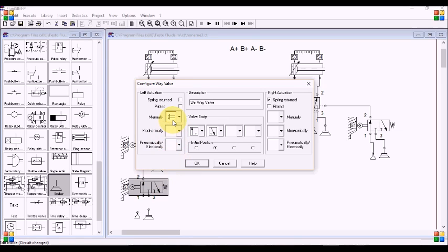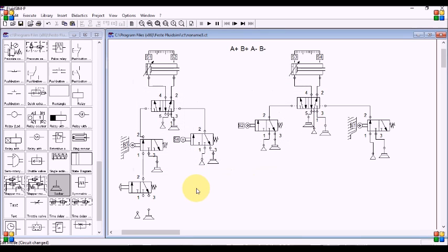If I keep this push button, it would be for one cycle. If I want to make it a continuous cycle, I have to use this push button with a detent switch. Again, you can refer to my earlier videos for all these basics. So now I'll be using one push button with spring return. Once I click the push button, only then the circuit would start. You can just have a look, see, once I push it, S3 is true, that's why it goes here.